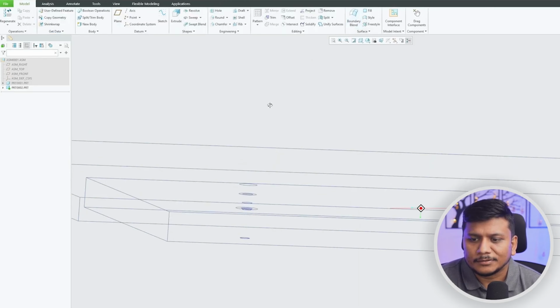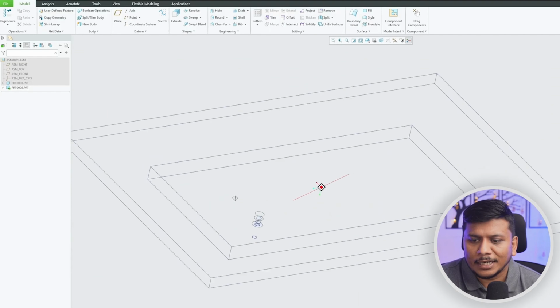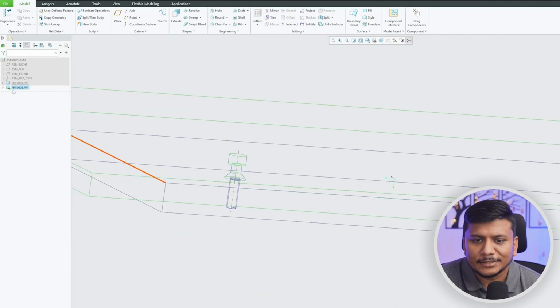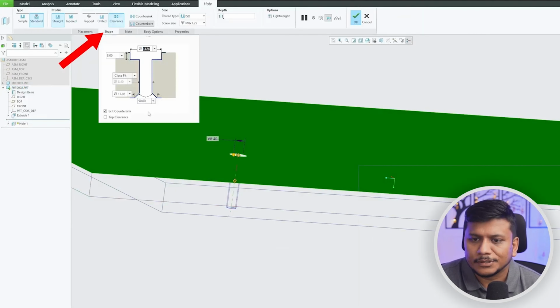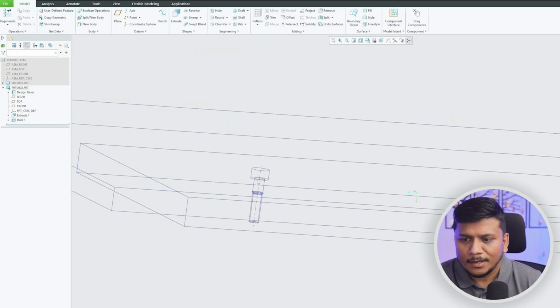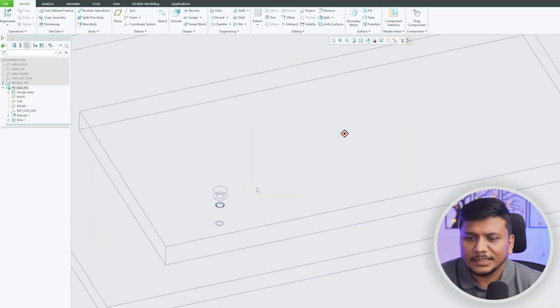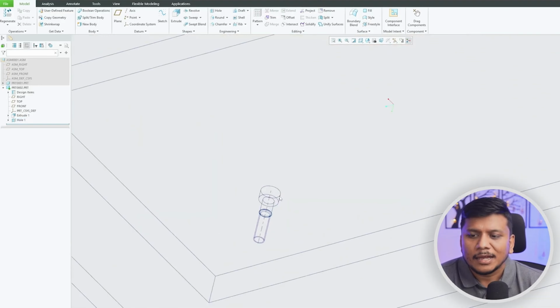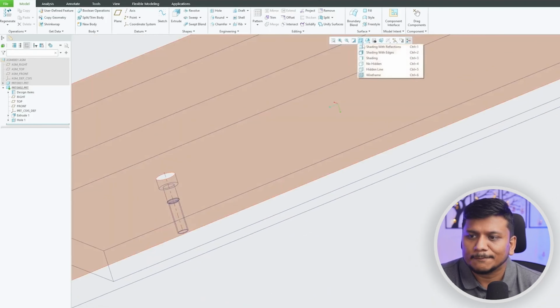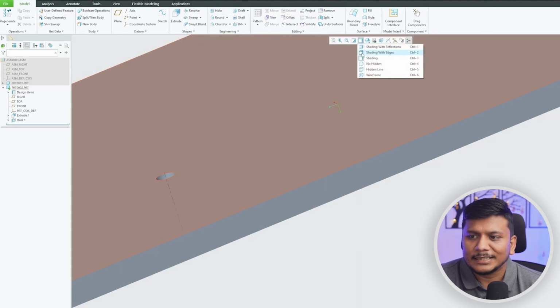Now let's click OK. And there we go, guys. Here we can see, although I think I have added a very huge countersink. So let's actually fix that. Let's go to shape, and here this value is 8. I'm gonna make this one at 9.5 at max, and let's hit OK. And there we go, guys. Here we can see we have added a perfect clearance hole type for this tapping hole in the below plate. So in this way, guys, we can utilize this axis hole.